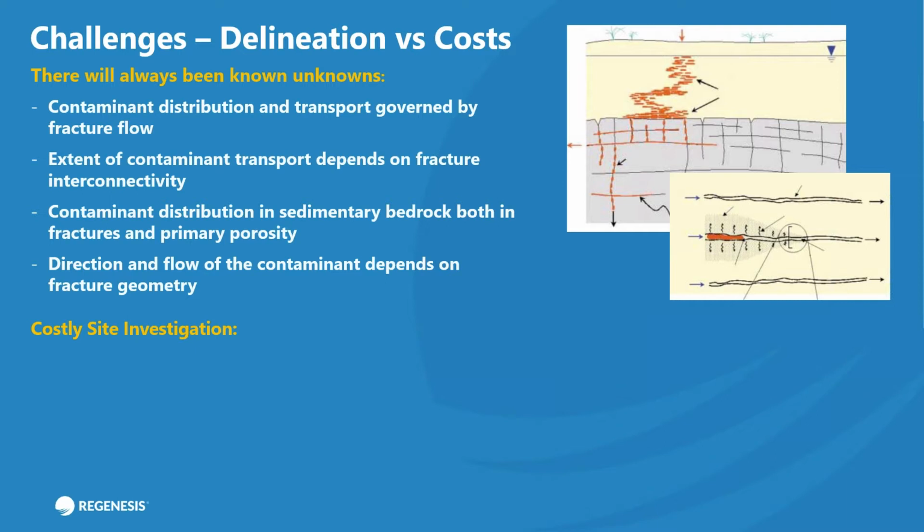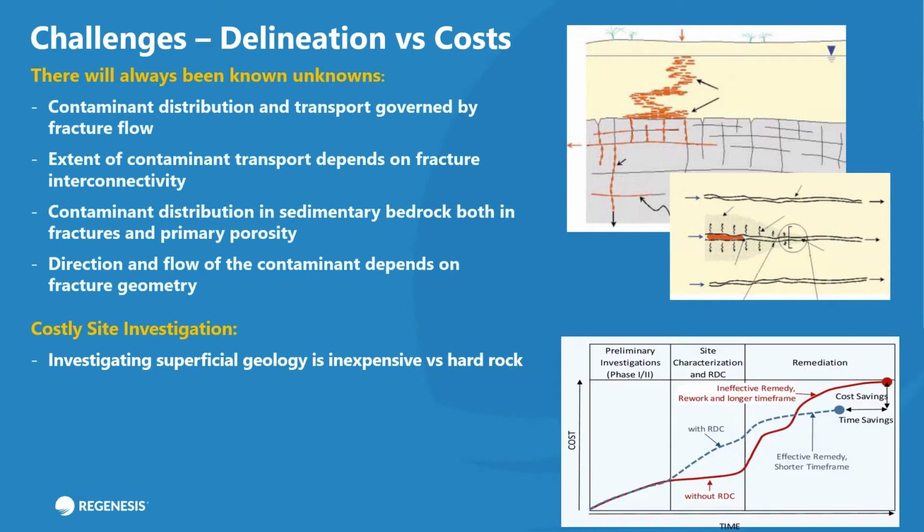Sometimes the contaminants will be behaving in ways that you wouldn't expect them to. I reviewed a site a couple of years ago in a Bromsgrove sandstone where we were dealing with free-phase petroleum hydrocarbons. The free phase, however, appeared to be diving, and that was down to the fracture configuration dipping on the site. So this is, again, something that's super important.